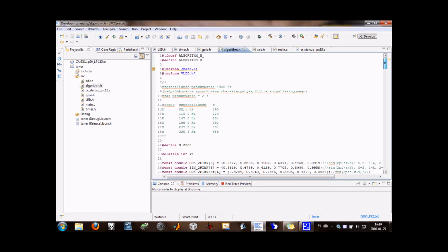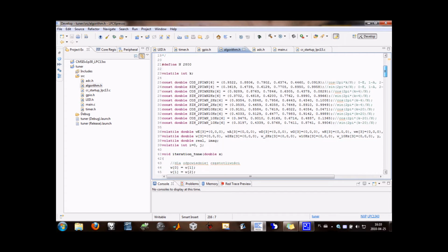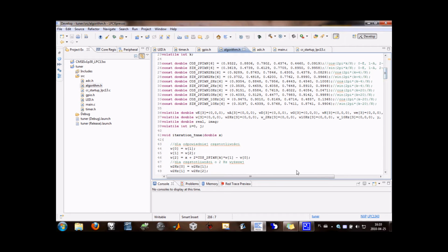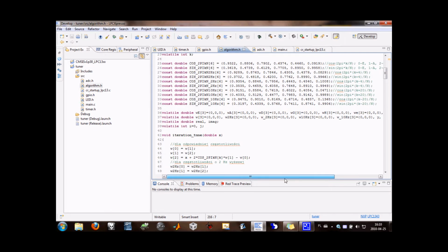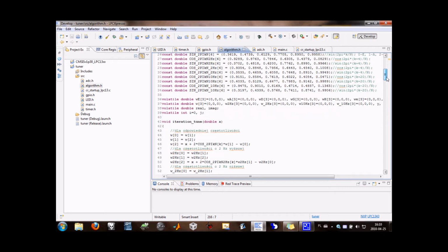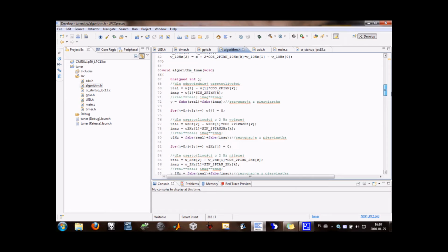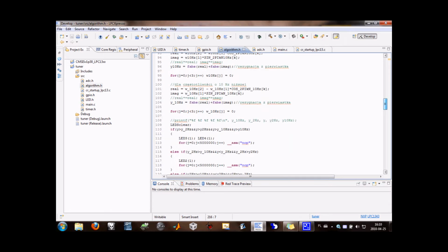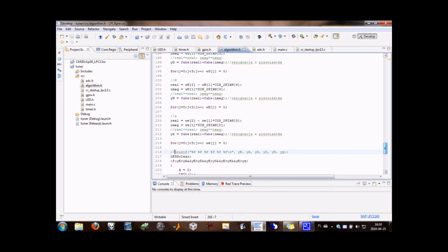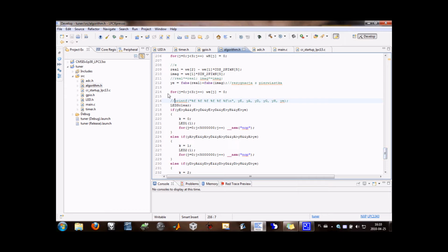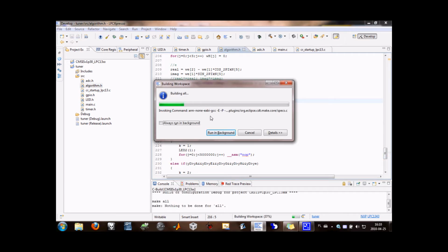Let's focus on this part, which is the implementation of a very simple Goertzel algorithm used to recognize the amplitude of a chosen frequency component. It works in real time without the need to store the samples in memory. I use the printf function to show the difference between the recognized frequencies of a signal generated from a computer.